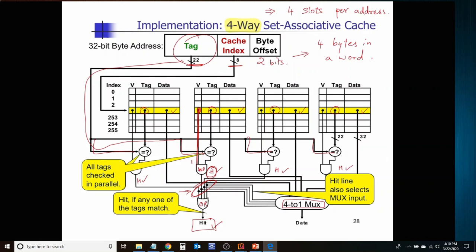So it's slightly different from a conventional mux in that a conventional mux will have 2 select lines to select from 4 options, but over here we have 4 select lines to select from 4 options. So you will have to slightly change the design of a traditional 4-to-1 mux, but you can do that. For example, if this is a 1, the combinational circuit that goes over here will pass that particular data, and if this is a 1, the next one goes through, and so on.